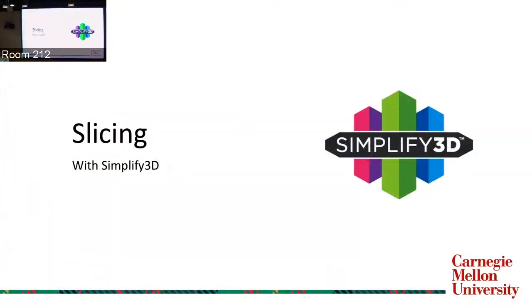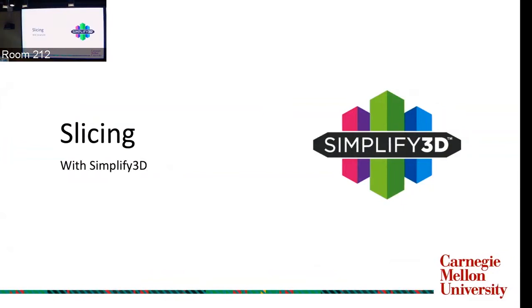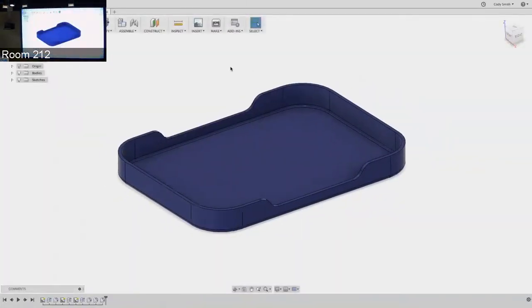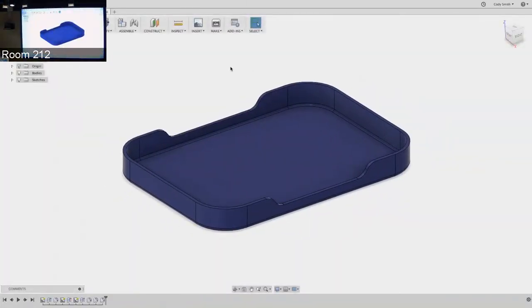Oh, sorry. For any structure that you're designing in this software, would you recommend doing a static or dynamic analysis, like the stress analysis? I mean, you could, because this part's bendy, and if I didn't want a bendy part, you could look at that and potentially put the material properties in there. Now, it's not going to model every little intricacy of a 3D printed part, because you tend to find that on layer boundaries you have less strength than in the layer, and we'll talk about that too.